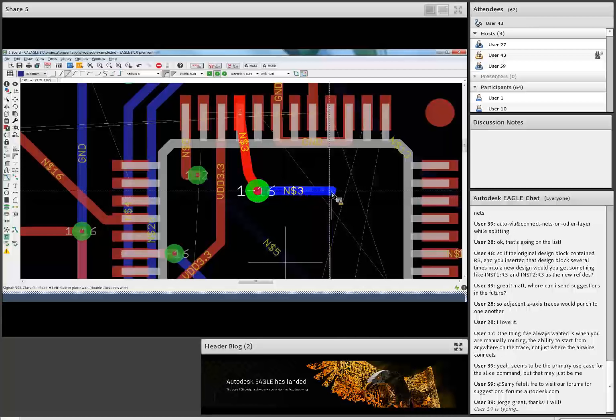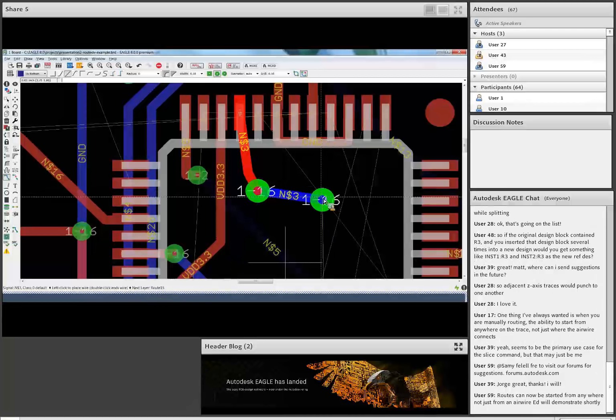But now, if you don't want to use a center mouse button, let's say you're working on a trackpad and the center mouse button is not that easy to reach, then what you could do is hit the space bar. If you hit the space bar, please notice here on my status bar, the layer select is changing. So if I just keep on hitting space bar, it will give me different layer selections, and it's going to go in order, 1, 2, 3. So it'll go from the top of your list to the bottom of your list.